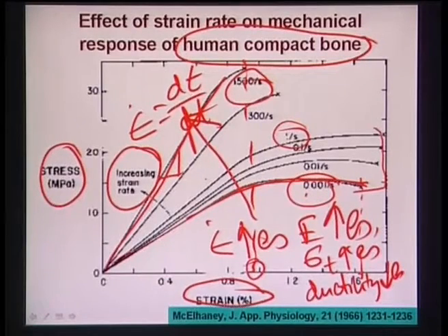Now, the question is why it depends on the strain rate. The answer is, bone has a complex composition. It has some water, about 9 weight%. The majority is hydroxyapatite, that is 69 weight%. Then you have collagen content around 22 weight% or so. It is a polymer-ceramic composite.